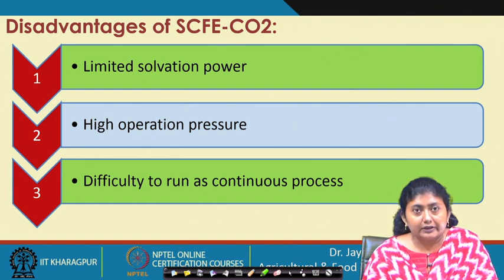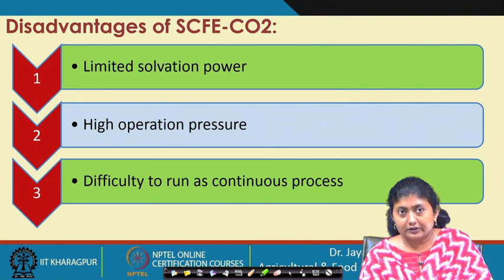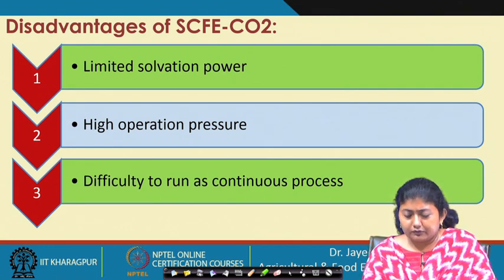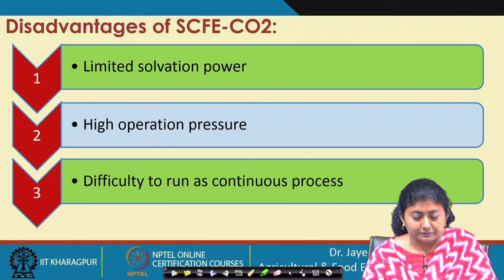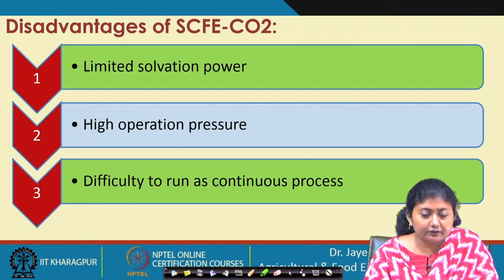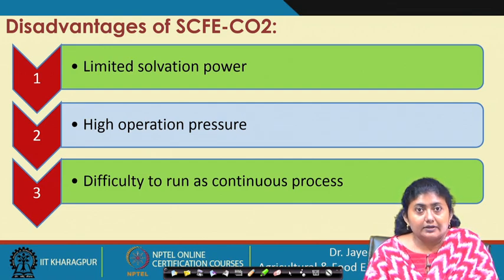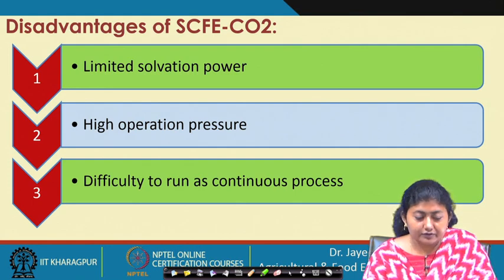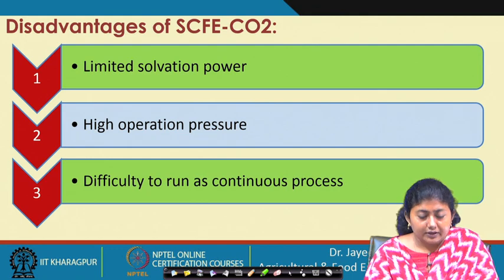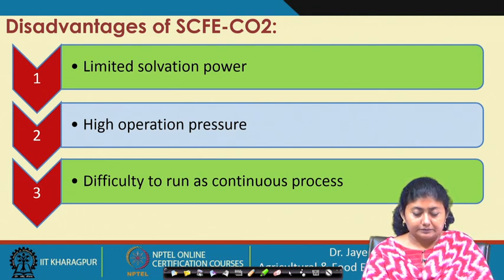So, there actually 85% of the energy of the whole process is being spent, while for extraction we generally use 15 to 20%. If we use supercritical fluid extraction, maybe that separation has no cost involved, because we can very easily separate by lowering the pressure. So, the extra cost that we reduce there can be utilized for the initial setup. That way it is very beneficial.